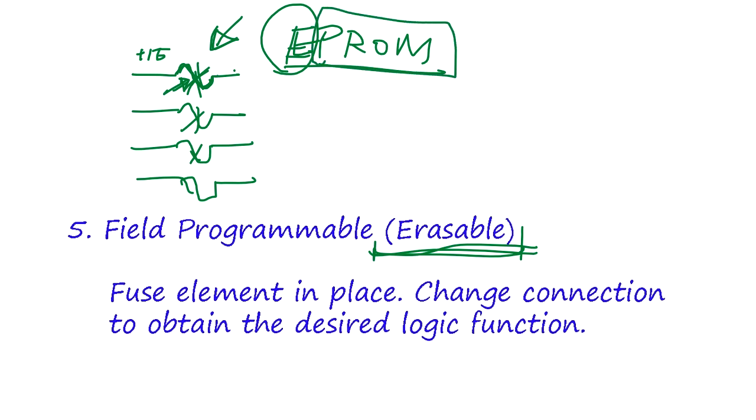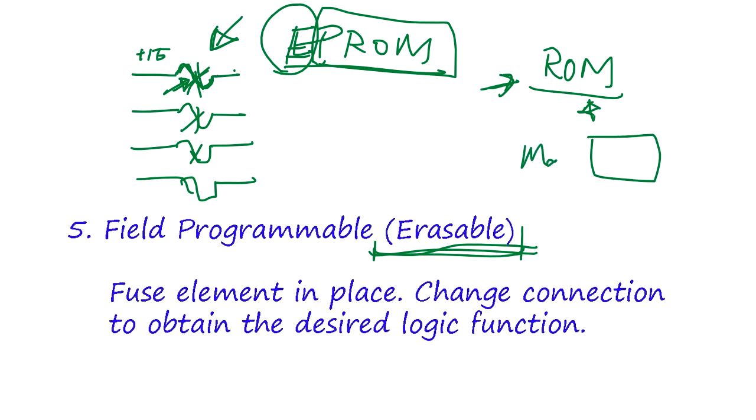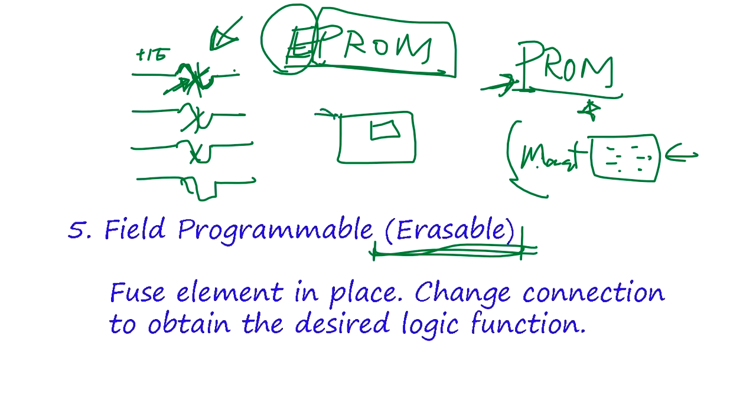Field programmable is convenient because with a mask ROM, in the manufacturing process, one layer of the mask is programmed and used. But with field programmable you don't need any custom mask. You just put the chip in the machine and specify which ones to be programmed, and you get the programmed ROM. Okay, so that's another type of IC chip.